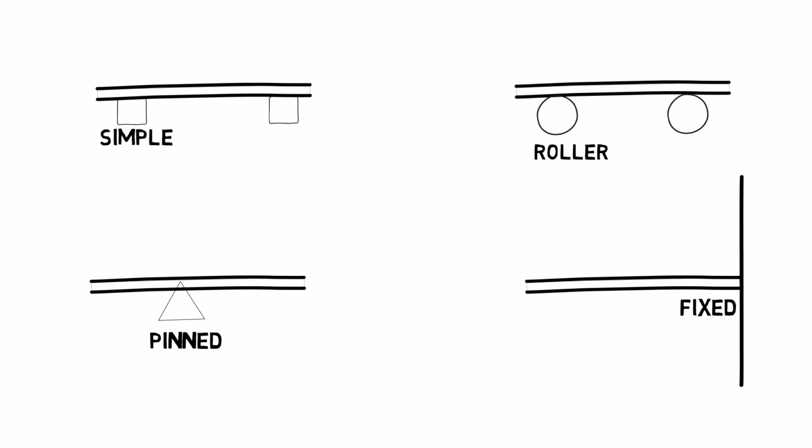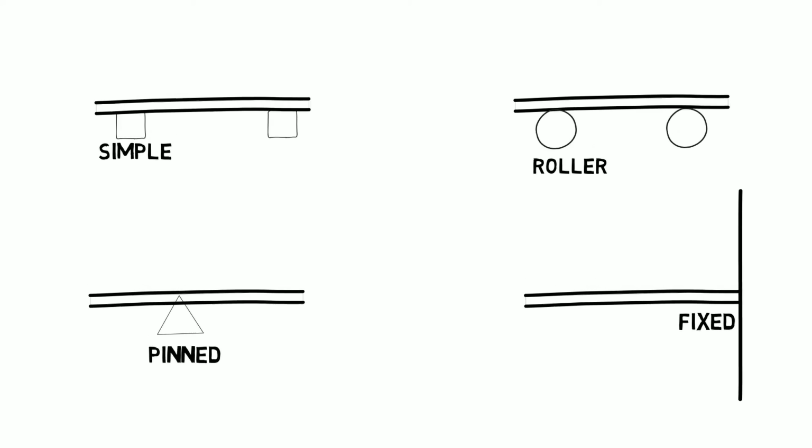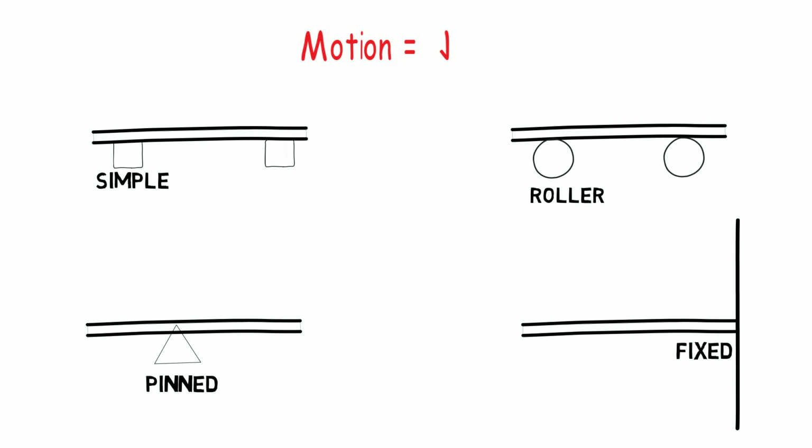The important point to understanding the reaction forces is to check for the direction in which the motion is restricted. If the beam moves in the direction of the force applied, it means there will be no reactions in that direction. Keep in mind that you have to assume the beam is rigid and would not bend or break no matter how big the force is applied. Let us start with a simple support.